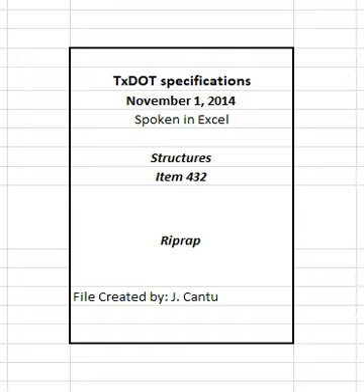3.2.2 Type F. 3.2.2.1 Dry placement. Construct riprap as shown in Figure 2 on the stone riprap standard. Set the flat surface on a prepared horizontal earth bed, and overlap the underlying course to secure a lapped surface. Place the large stones first, roughly arranged in close contact. Fill the spaces between the large stones with suitably sized stones placed to leave the surface evenly stepped and conforming to the contour required. Place stone to drain water down the face of the slope.